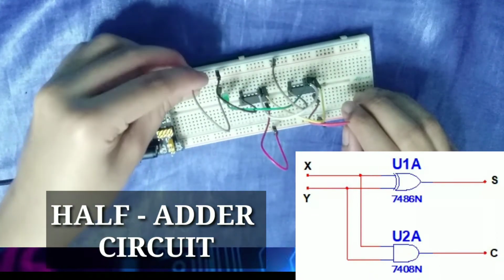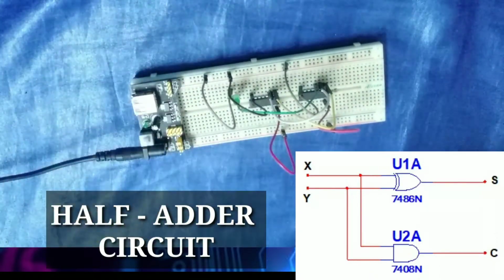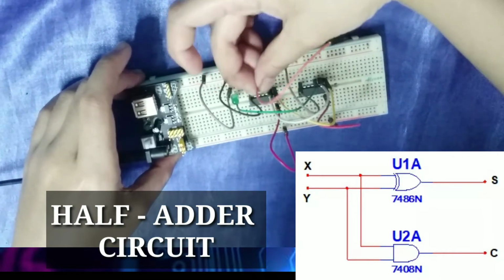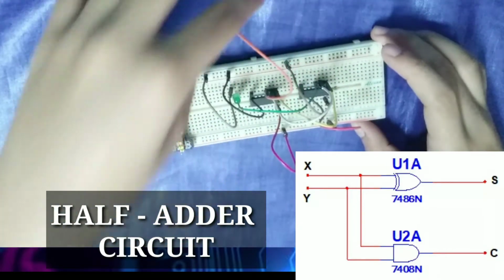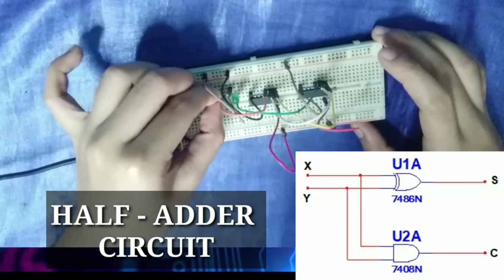And after grounding, we will be putting the output for the carry, which will be from the 7408 IC, from the third pin of the 7408 IC. Let's put it here.